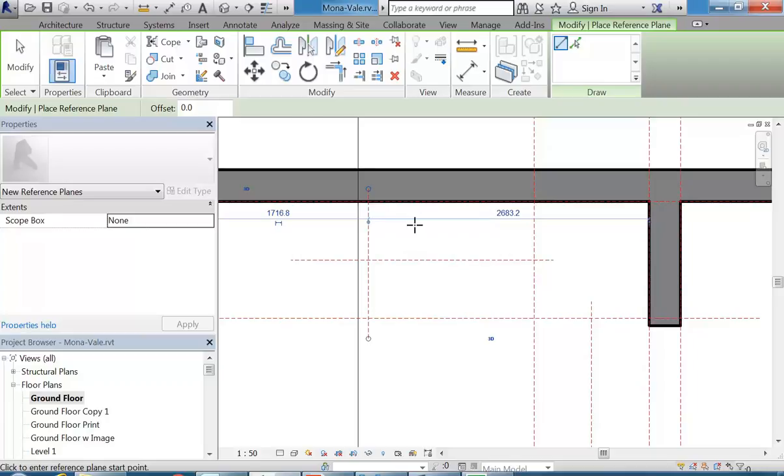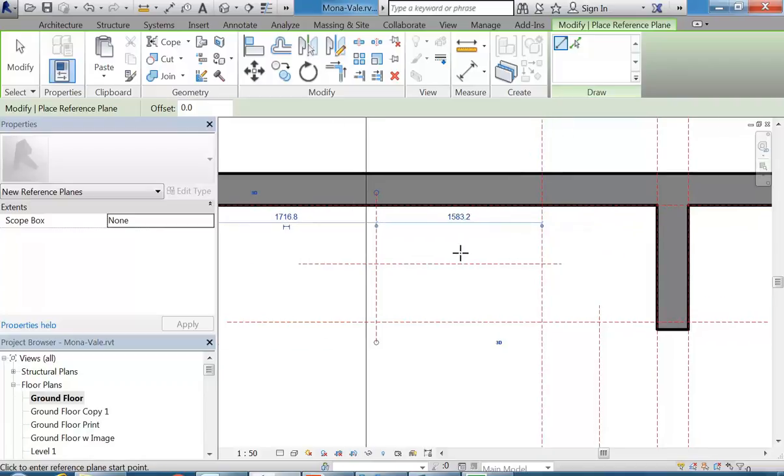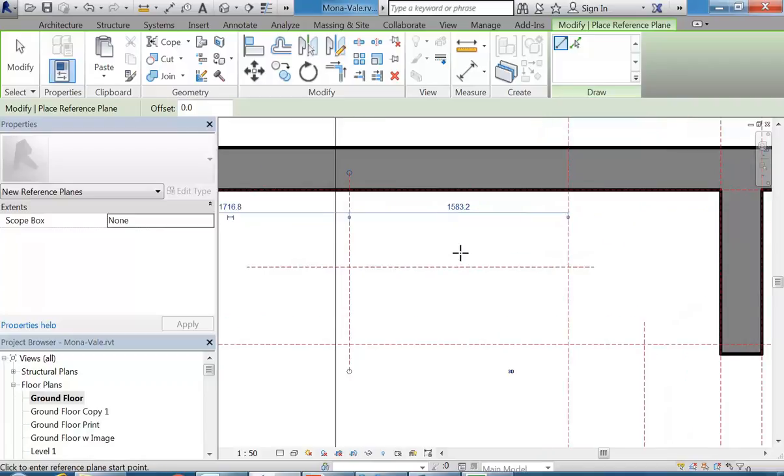Yeah, 25s. Oh, that's your 2R plus G. That's an extra calculation you can do at the end. But 250 mil is standard for public stairs. Private stairs you can go down to 240, but it's good if you can just keep it at 250. So I'm going to keep in multiples of 250, and then I can make this say 1500.